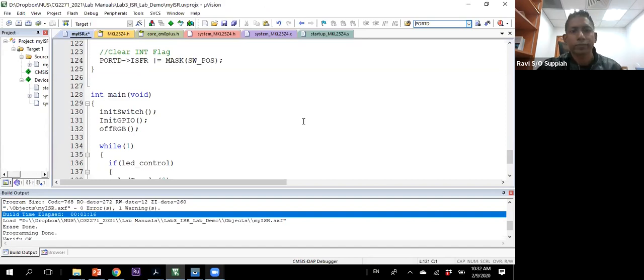When you observe it, you have a rough idea of how long the debouncing period is. One easy way is to buffer or put a delay until that time lapses, so that you get past the debouncing and don't get any false triggers. That is of course a very simplistic solution to going around the debouncing issue. That is what I want to show you, and what you need to be doing and preparing for the lab.